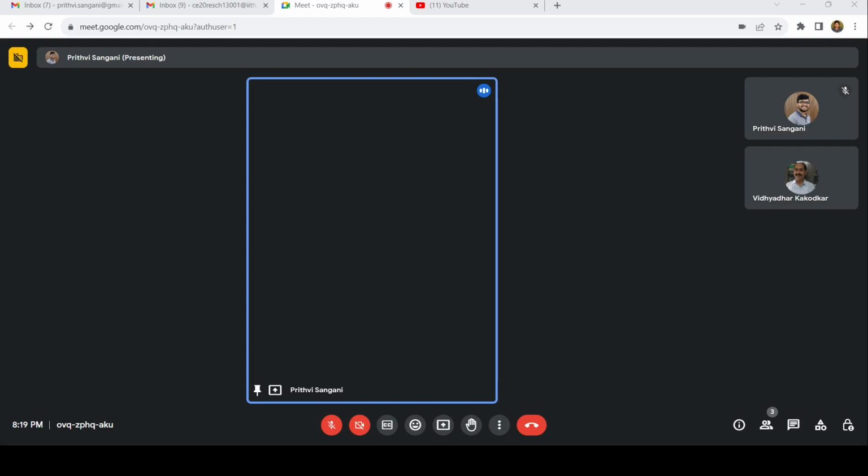In this question they also mentioned E is 200 GPa. Usually trusses have metal members, right? Because we assume hinged connections, it is very difficult to get a hinge connection for concrete members. Anyways, we can't utilize concrete in tension, so that may be one reason we can't use concrete for truss members. Whereas metals have the same behavior in tension and compression.